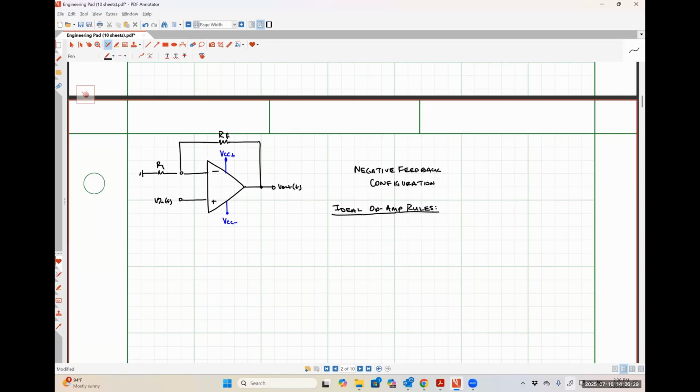If you want to get into the nitty-gritty of it, you can watch my videos where we talk about negative feedback in circuits too. But realistically, even for a poorly designed op-amp, when it has negative feedback in place, you will only have less than 1% error if you just assume it works as an ideal op-amp. So we're going to assume that all of our op-amps in this class are ideal.